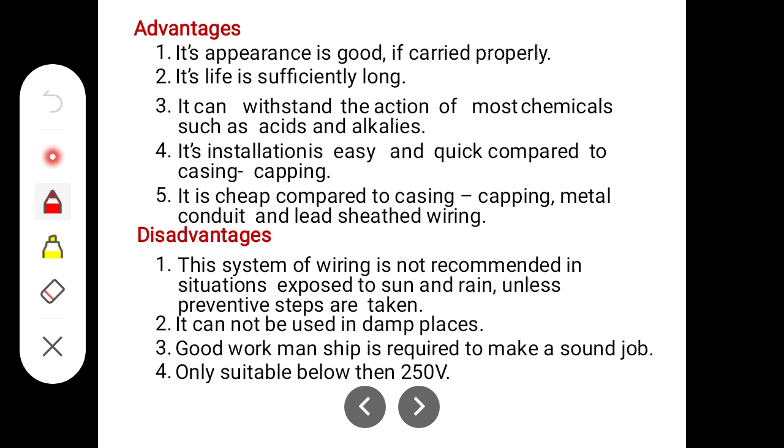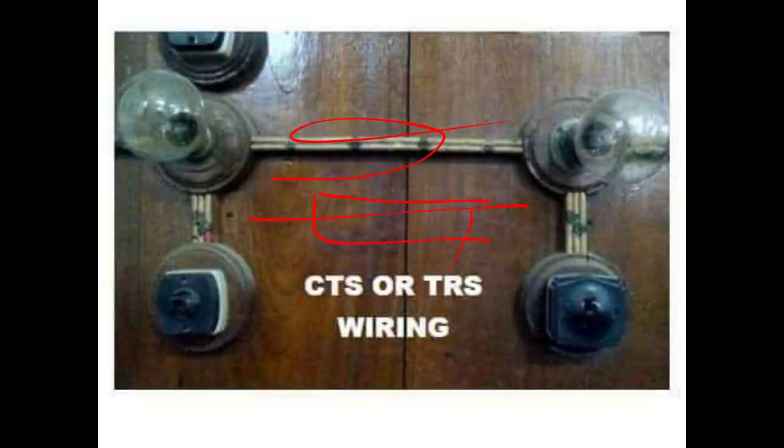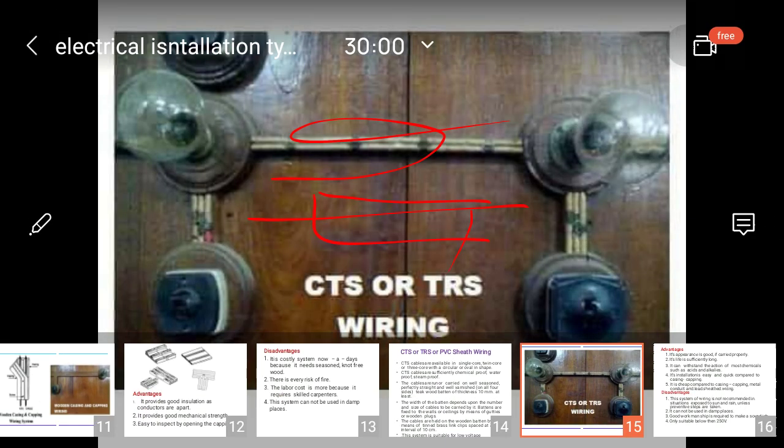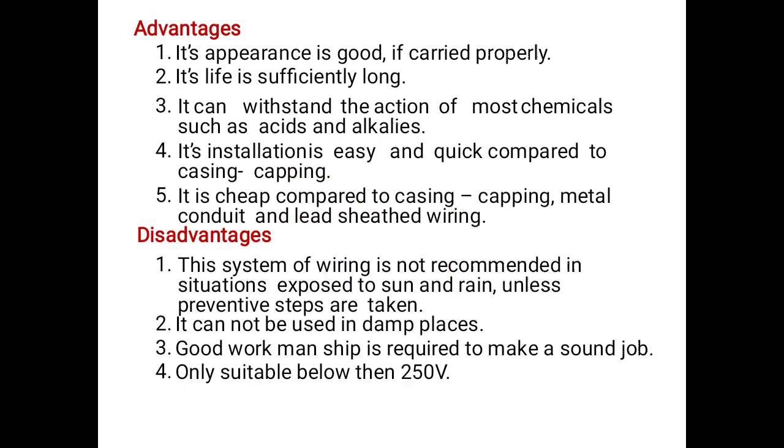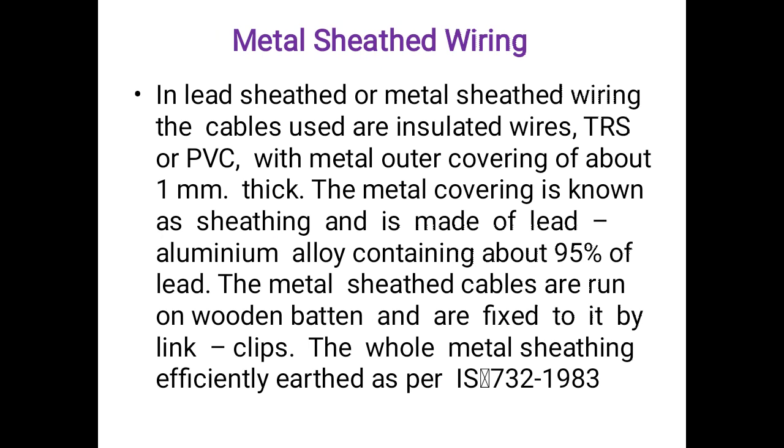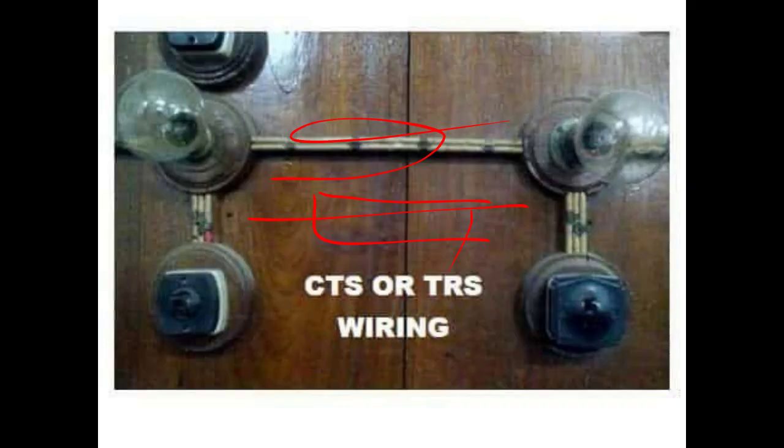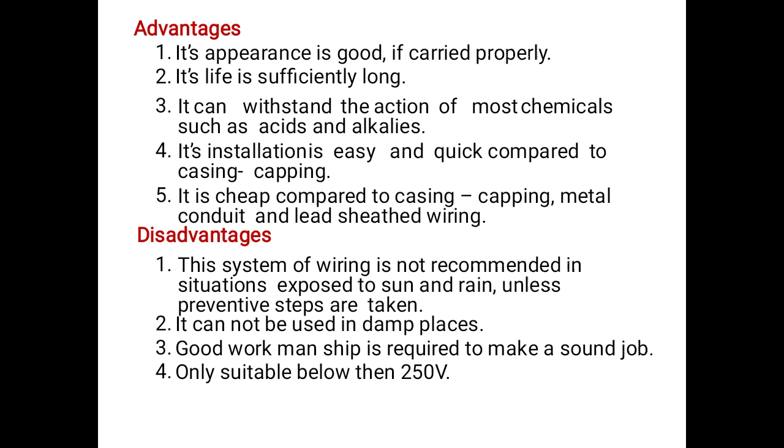So here are the advantages. The appearance is good and carried out properly. The life is sufficiently long. It can withstand most chemicals such as acids and alkalis. Installation is easy and quick compared to casing and capping, and it is cheaper than casing and capping and metal conduits.